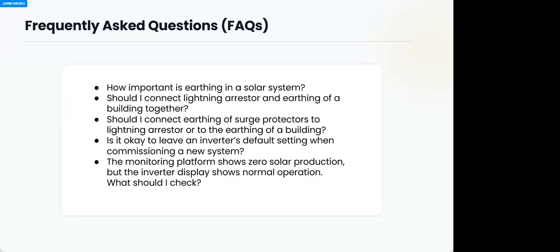But the lightning arrestor cable will go straight to the ground. It does not go inside the building for any reason. It doesn't go to the inverter stand. It doesn't go to any connection. It goes straight to the ground. So whatever it captures, whether it is what it receives from the frame of the solar panel or the one it captures directly, everything channels to ground. So you can connect the frame to the lightning arrestor up there, or better still, more professionally, you connect the frames straight to ground separately. That's more professional.